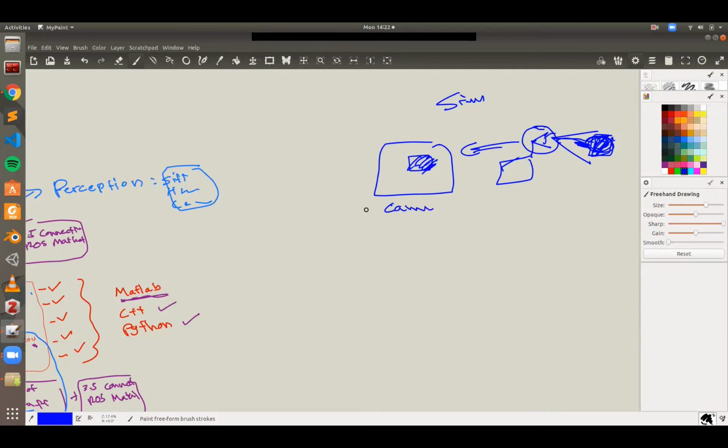It'll be a simulated camera image in the sense that the object is simulated, but from ROS's perspective, what it will be giving out is a camera image, right? It doesn't know whether this was a simulated object or not, but it's created a photograph of that object as if that object was actually there. So to do that, you need a simulation of that object in front of the camera, right? And you can't really do that in RViz, right?